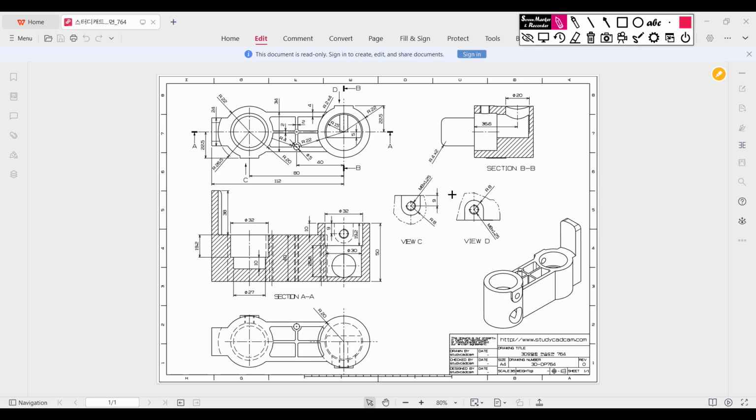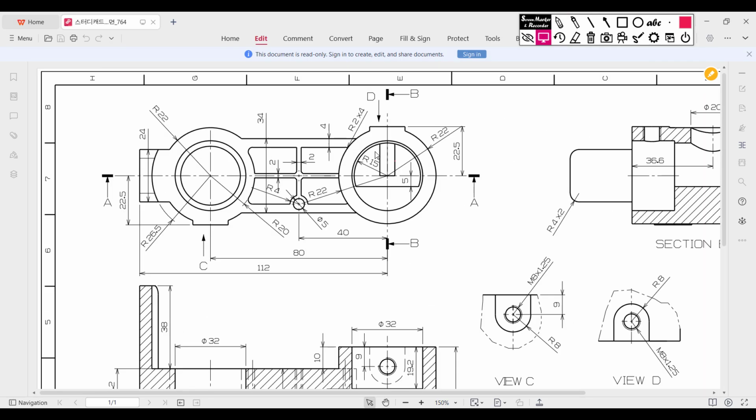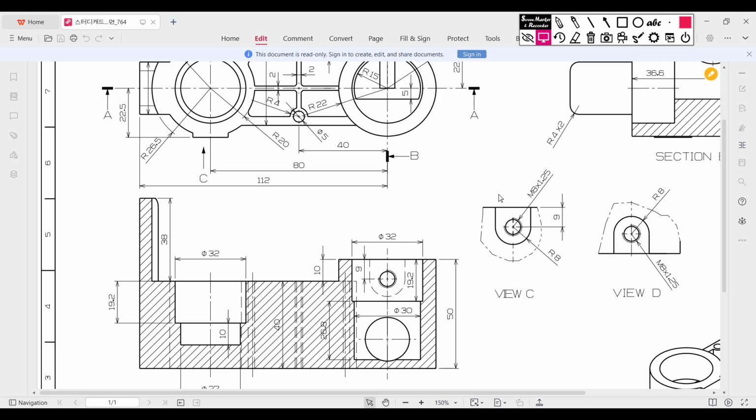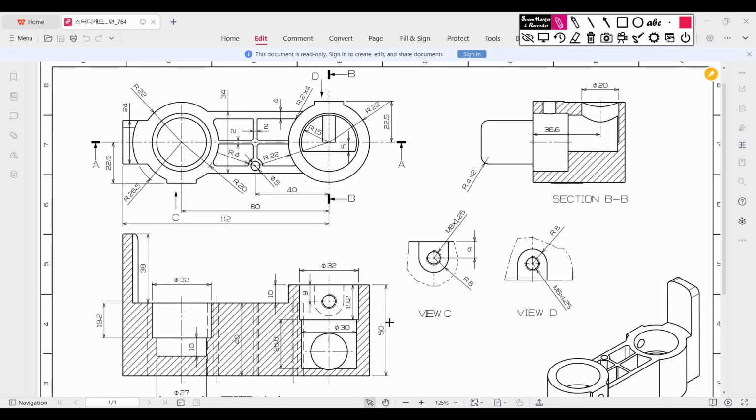First of all, in our drawing, we will start drawing from the top plane. Okay, let me zoom in a little. Let's go. First of all we'll draw this circle, and this circle has a dimension of 22 radius, so its total dimension will be 22 multiplied by 2. It has to be extrude boss of 50 unit. After drawing this circle on the top plane, we extrude boss it to 50 unit.